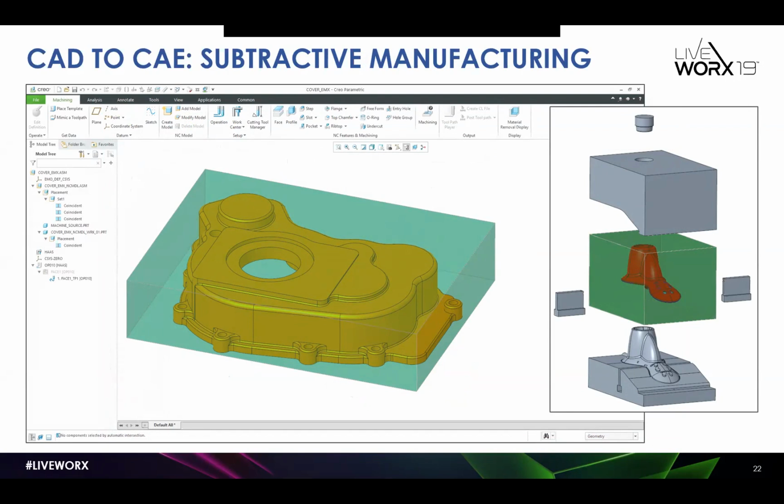First, traditional subtractive manufacturing like CNC machining. Teach them some basic Expert Machinist, Pro-NC, and mold design. They don't have to do the full-blown manufacturing process, but spending a little bit of time on this will teach them how to avoid complicated fixtures, excessive setups, rounds on the wrong edges, non-standard hole design or hole diameters, excessive undercuts requiring sliders, and inadequate draft to release a part from a mold.